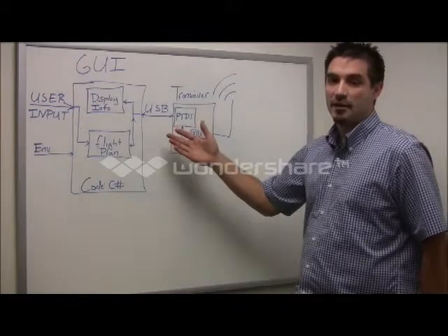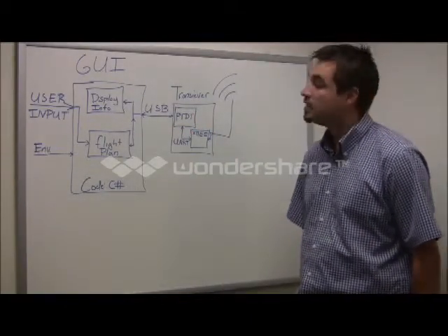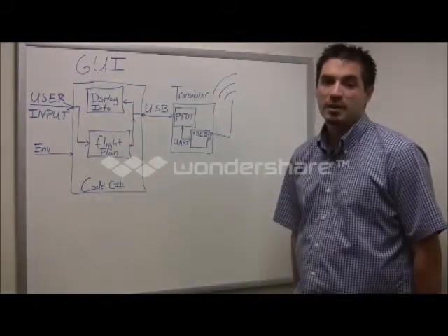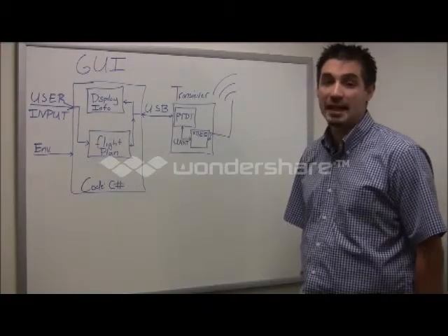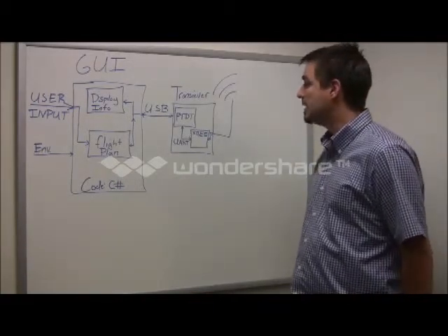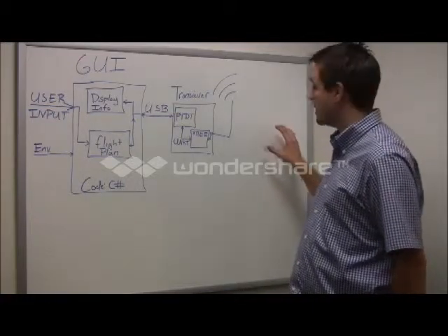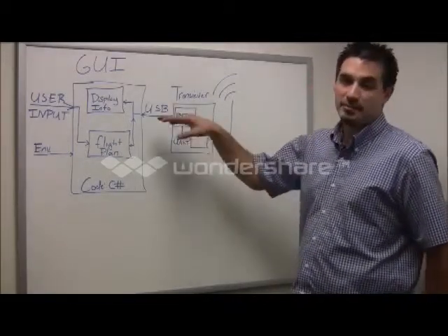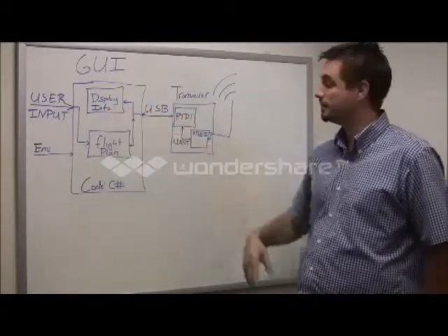This is the block diagram for the graphical user interface portion of the UAV project that is written in C#. First, we have a display console that displays the current latitude, longitude, altitude, land speed, and GPS signal. This information is transmitted from the main processor on the UAV through the XBee using FTDI. It is transmitted into the computer using the USB and then displayed on the console.